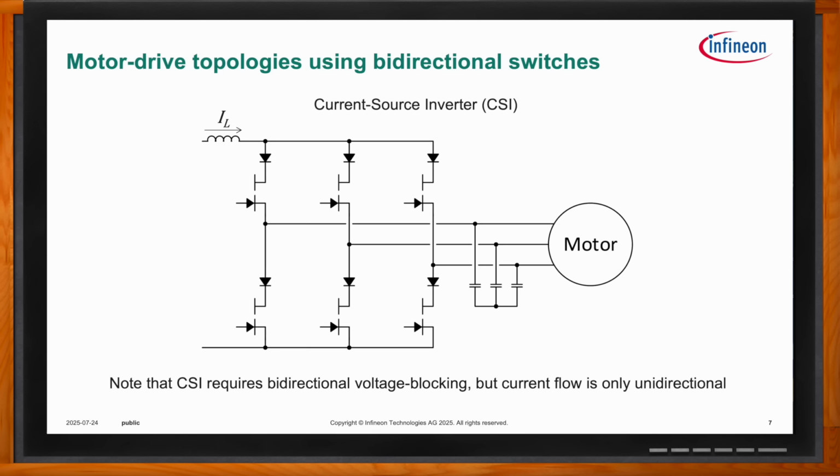So, Eric, this really doesn't look any less complicated than a standard voltage source inverter used for motor drives today. What is the motivation for using this topology? What are the benefits here? So once again, always a compromise. You do need a current source front end for this that drives the inductor current. As I mentioned, you get sinusoidal voltage to the motor and you eliminate those bearing currents.